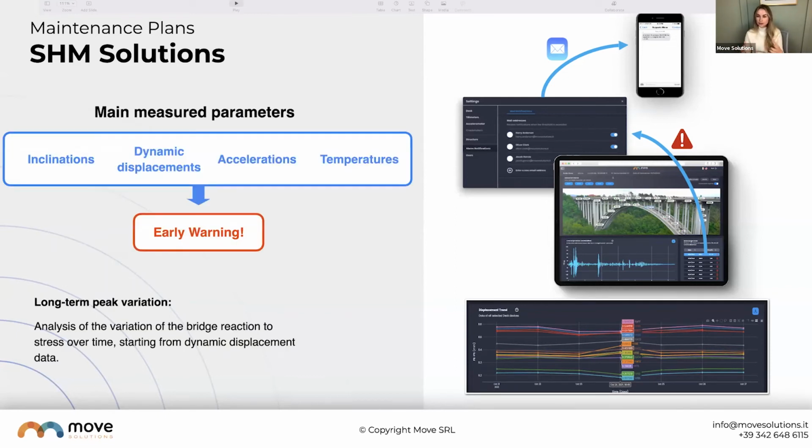So this is important with the life predictions of the structure, and also understanding that structure over time. So that's taking all of the dynamic analysis and understanding the trends over time, performing the modal analysis, understanding the displacement trends of the structure, and understanding over time if there are changes, if they're related to certain weather conditions, seasons. If there is a problem with the structure, you're able to see that over time.